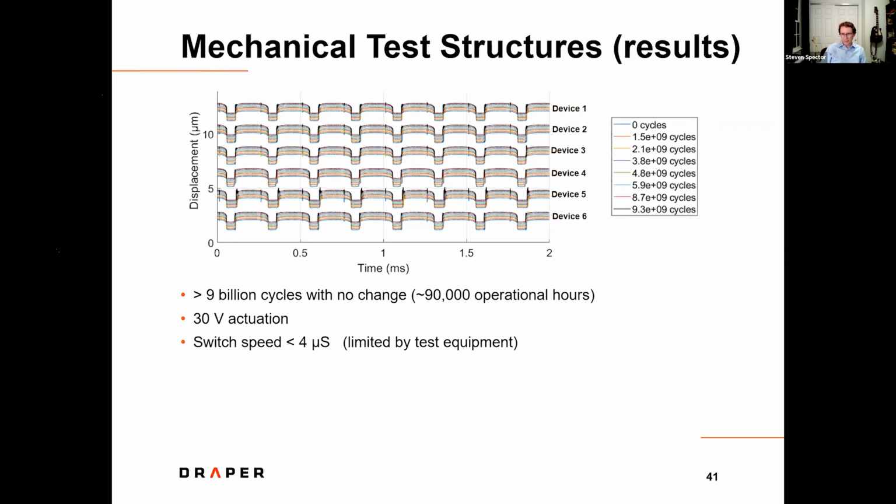So it certainly can be done, and it is done. It's just a different technology, and as I mentioned, the disadvantage is that your VCSEL can only have so much brightness. With an edge emitting laser, you can have a much brighter source, so you can put a lot more power at a small spot, which can allow you to get to greater range. But the VCSEL is a completely legitimate technique of doing it, and people are doing it.